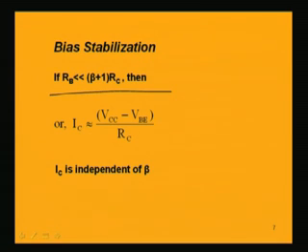So, that means we are making this IC independent of beta after meeting the design specification in this way. So, this is the key design condition we have to meet while designing this biasing scheme, and then we can achieve IC being insensitive to beta.